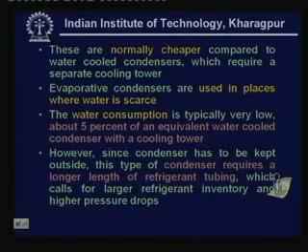However, the disadvantage of evaporative condenser is that since the condenser has to be kept outside, this type of condenser requires a longer length of refrigerant tubing, which calls for larger refrigerant inventory and higher pressure drop. So, this is a disadvantage.